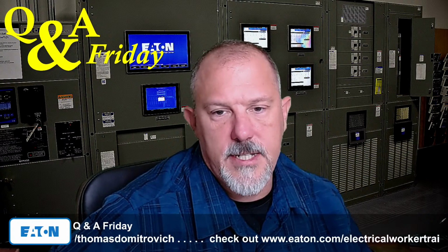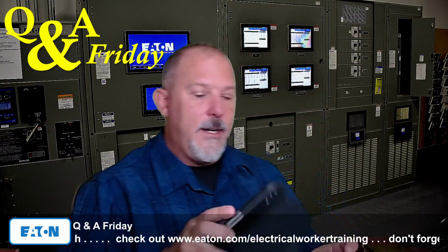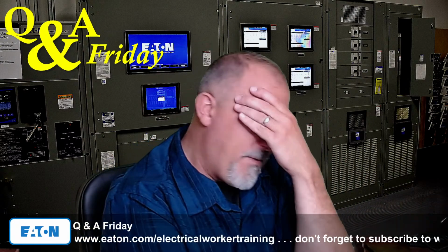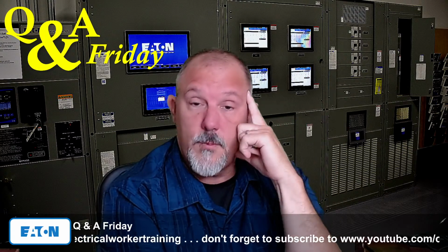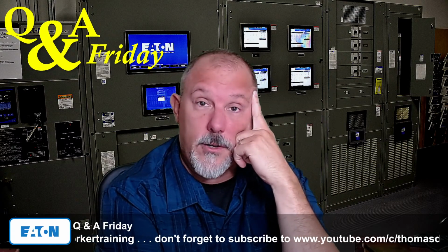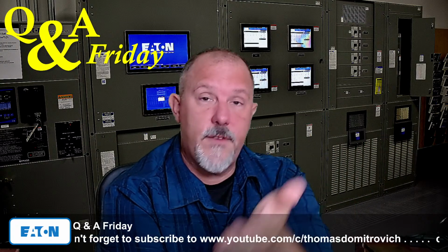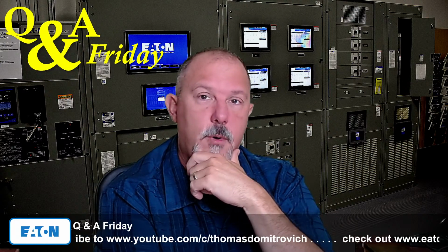Let's go up. They should put some arcing current calculation examples into the annexes for the NEC. So here's JW. Here's my thoughts on that. I think the first thing we have to do is probably put a definition of what an arcing current is. We have a definition for available fault current, but we don't have a definition for the available arcing current.